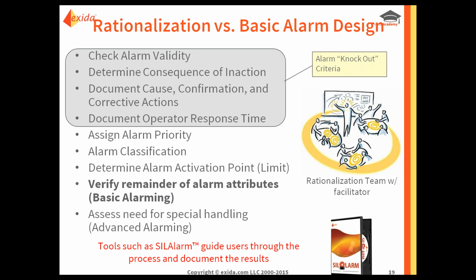Certainly, rationalization can be a pretty resource-intensive process where you've got operators and process engineers in there, and you might find that discussion of alarm deadbands and on-off delays doesn't really require them, which is why those discussions were not considered to be part of the rationalization process when the ISA standard was created.